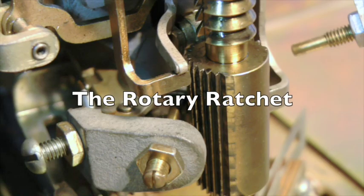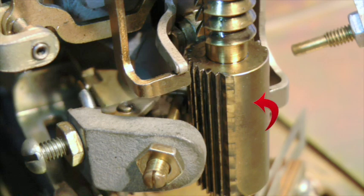Immediately below the vertical ratchet is the rotary ratchet. The rotary ratchet is one of several devices involved in rotating the shaft horizontally clockwise, one step at a time. The ratchet has teeth which are engaged by a pawl to rotate the ratchet. Each step will move the wipers to an adjacent set of bank terminals. Here's a slow motion clip of the ratchet being rotated 10 horizontal steps.